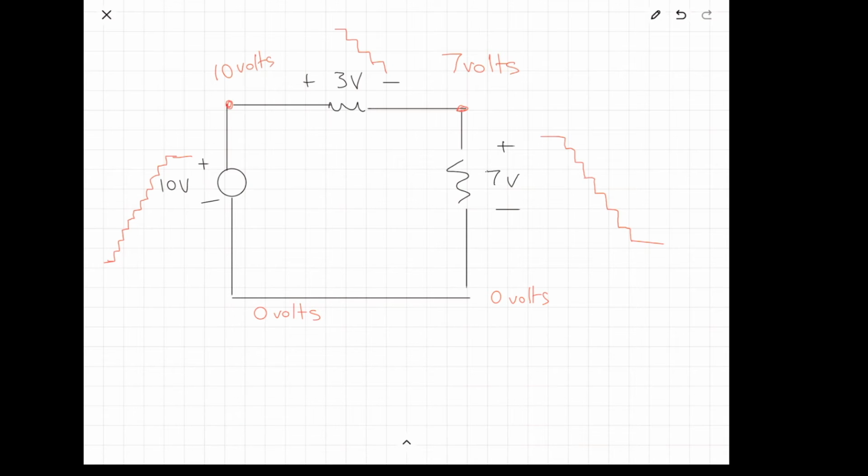We can take any loop around a circuit, any closed loop, and it will be true for it. Okay, it doesn't matter. There's no special conditions for it, really. By the way, in this case, I took my loop as being around in this direction, clockwise. I would suggest that you pick a direction and always stick to it. I always use clockwise. I never use anti-clockwise.